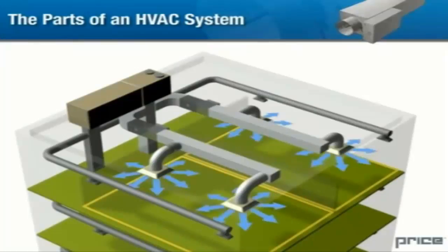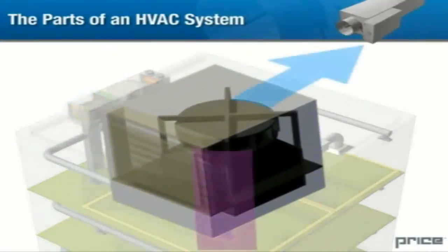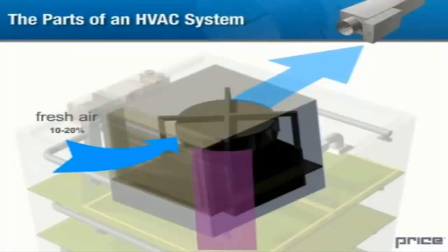Once air enters a space, where does it go? Air circulates through the return inlets and returns to the air handling unit. Unlike an air outlet, a return requires no sophisticated vane. However, the relative location of the air inlets and outlets can be critical to the efficiency of the system. Upon returning to the air handler, a certain portion of the return air is exhausted and replaced with fresh exterior air, in an average office building or commercial space, approximately 10 to 20%.